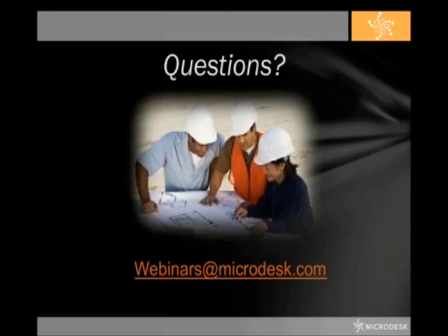Great. All right, and in regards to the electrical updates, could you do a quick summary of what some of those changes were this year? Okay, on the electrical side, you're going to see that the room calculation points were one of the big ones. You have the ability to move that lighting calc point from the lights into the spaces. So that's going to read all your IES files, any of the information you have in the lighting, and transfer that over into the spaces to do more analysis on it.